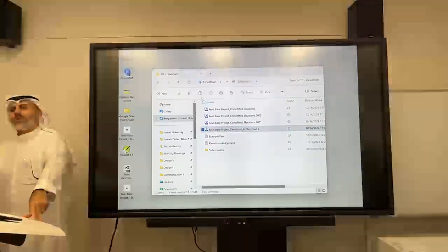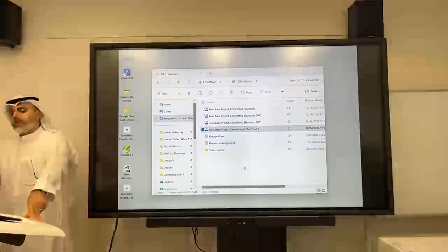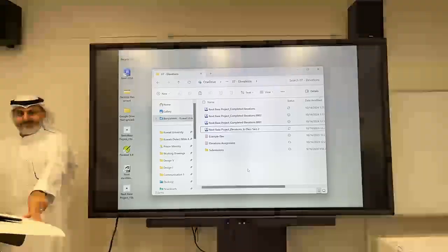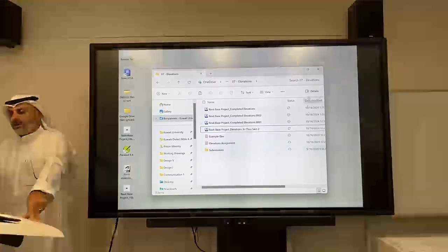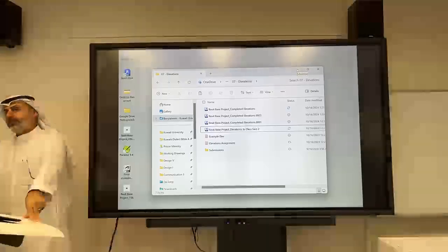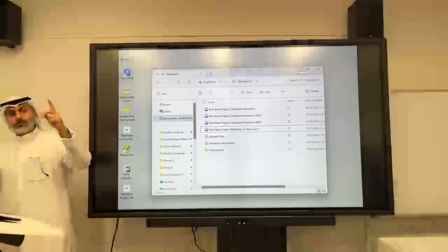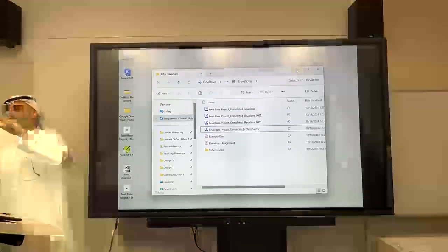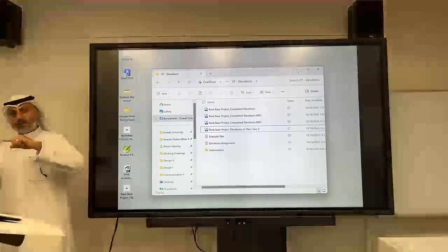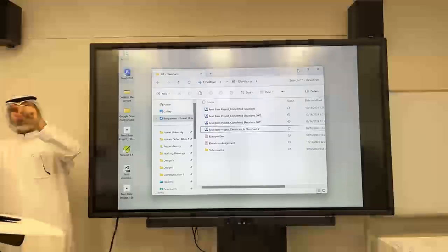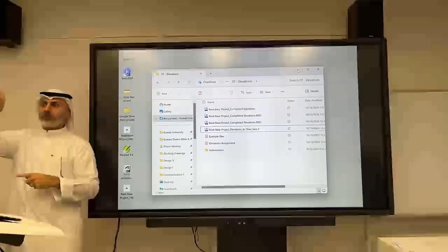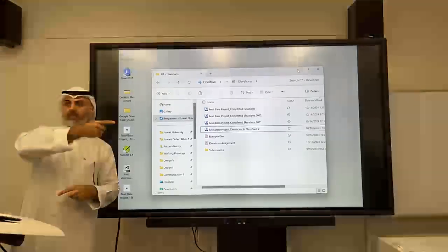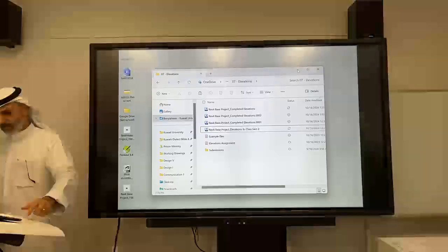In your floor plans, how many of you showed the columns? Okay, so if you haven't, don't worry about it, just show the columns, but also you need to make sure that they're not overlapping with the walls, and you can only find that out when you export PDF. In the Revit, you can see the column as concrete. It's when you export, you may see the wall overlapping the column with a hatch. So I'll show that now.